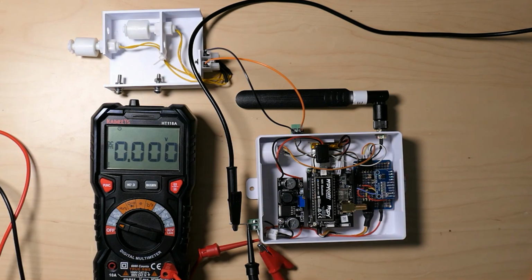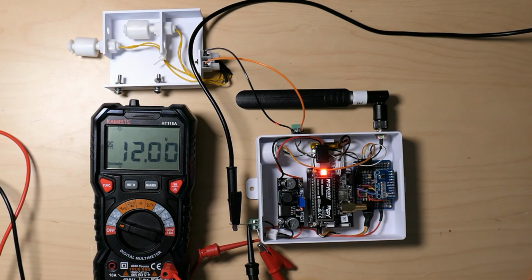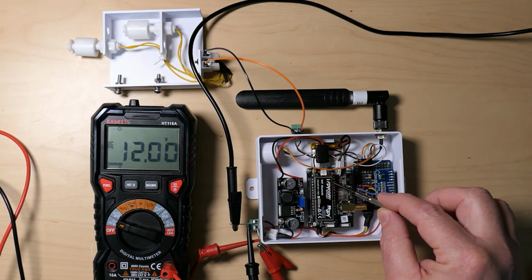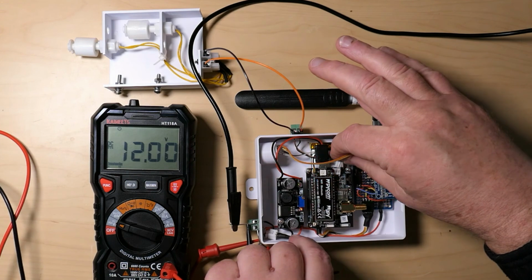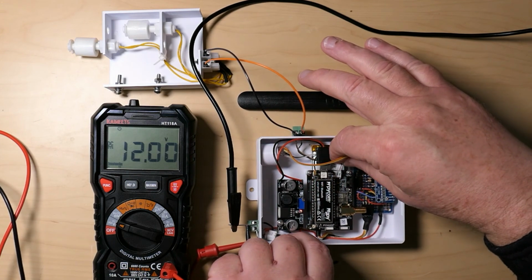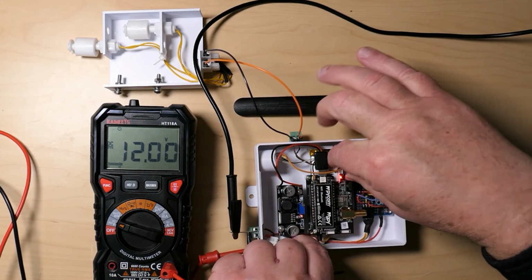So at the moment no power coming in. I turn that on. 12 volts coming in as though it's connected to the house battery, and we see it start up and the PyCom going through its normal sensor routine. So it's getting the GPS coordinates at the moment. That's the red blinking. Once it hooks into a satellite, then it'll change to green blinks while it gets some readings off the GPS. Let's plug in the lithium-ion battery.